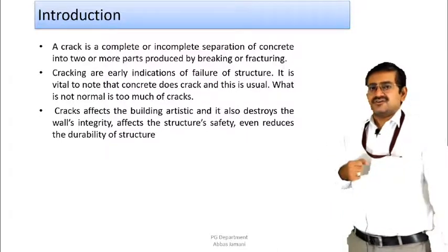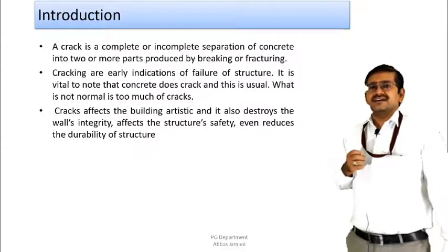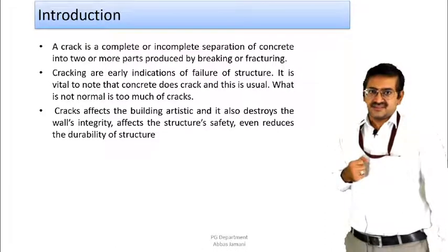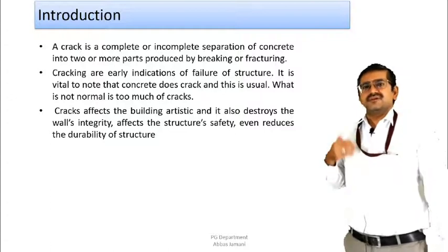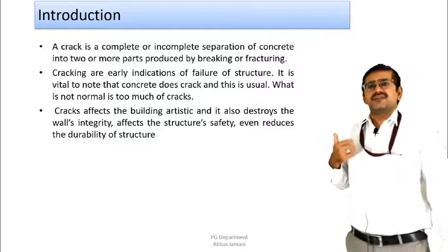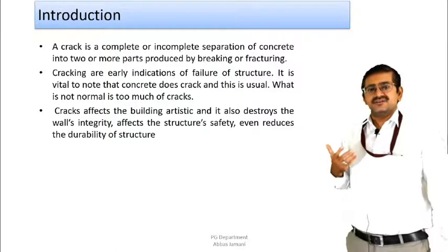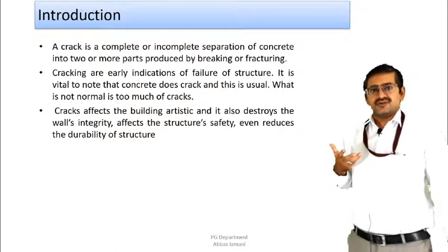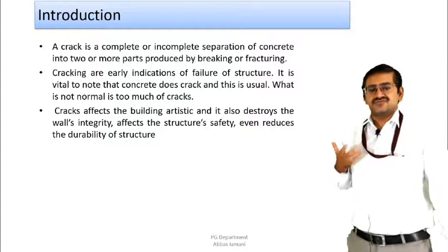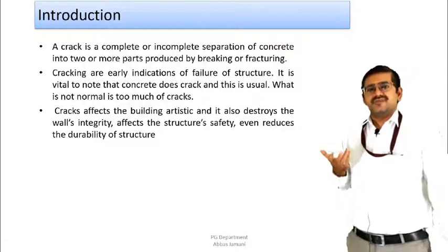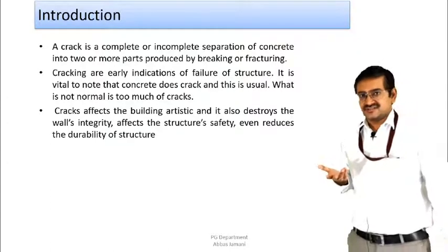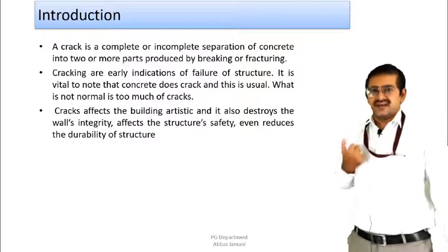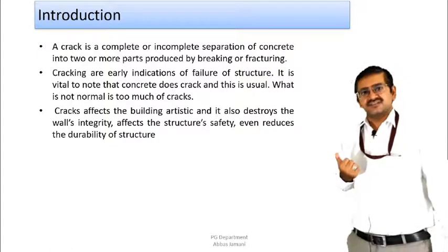Now, a crack is basically an early indication of the distress that has developed in the structure. As I said, the distress can be due to several reasons. It may be due to improper design, poor quality of work, or workmanship. Then it may be due to early removal of formwork, overloading, or the site conditions, soil conditions also. There are material issues also: the quality of the material used on the site, unavailability of skilled labor, and lack of proper site supervision, right?